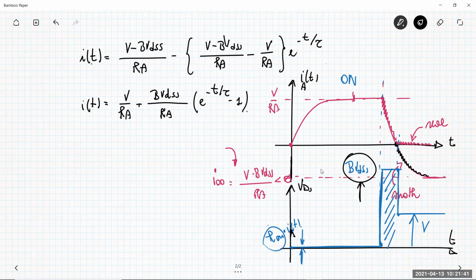In that specific situation, you are allowed to reach the maximum possible breakdown voltage, 600 volts, but this avalanche capability depends on the energy which is involved in this operation region. You have to operate in this region with a minimum amount of energy involved.